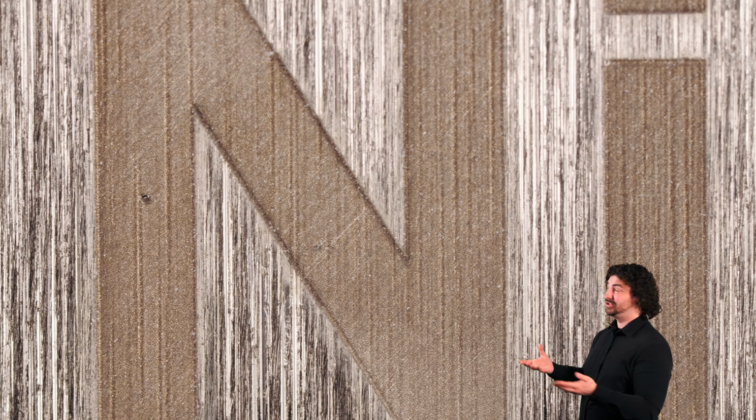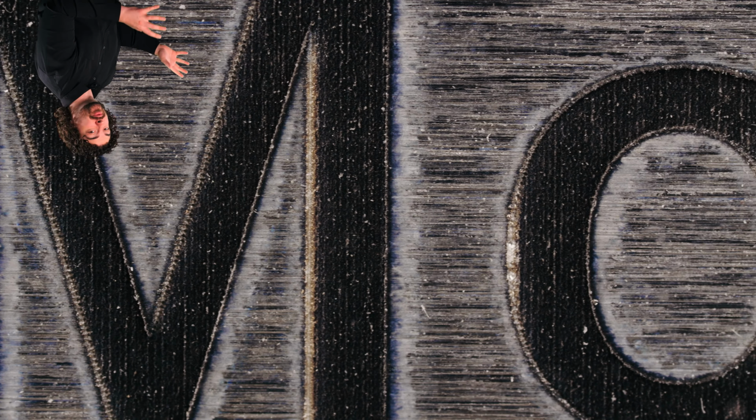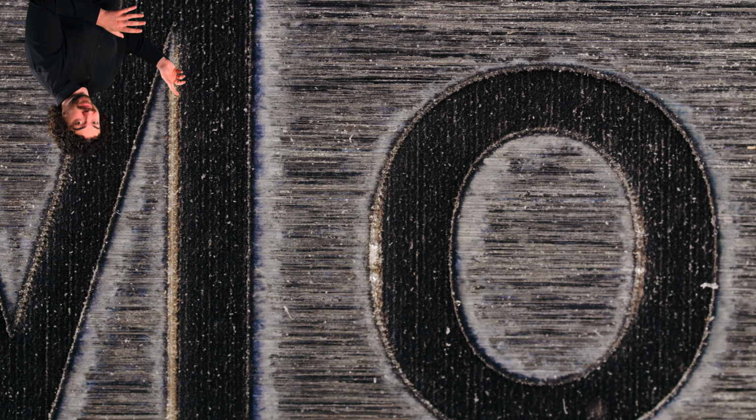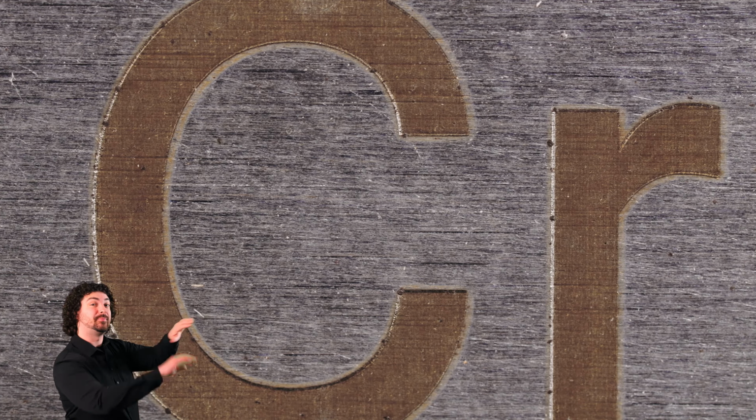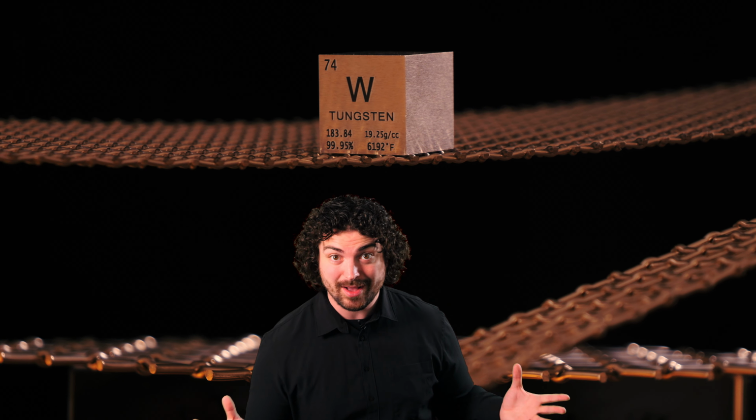But nickel in general is just really corrosion resistant. The molybdenum protects it from those really intense chemicals that make pitting and crevice corrosion a thing. The chromium forms an oxide layer that protects the mesh even more. And you want even more corrosion resistance? Boom, tungsten. It is literally in its makeup to not care about chemicals.